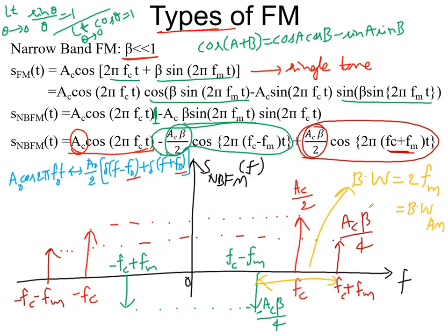This is currently the bandwidth for narrowband FM. But narrowband FM and amplitude modulation are almost similar. But anyway, whenever beta is far less than 1, it is of almost no use. This is only theoretically you are studying, and you may be using it for generation of wideband.